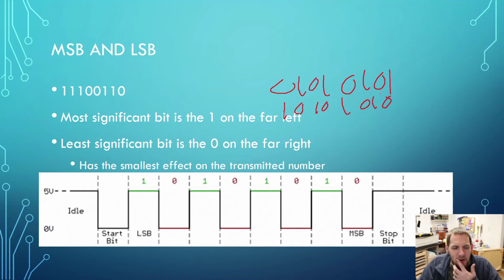So all of a sudden now your data is scrambled. You're like, why is it sending this information, what doesn't make any sense, what's going on here? It's supposed to be setting this specific code, and it's nowhere near that code. Well, that's because maybe it's your MSB or LSB. Which one are you reading first? So make sure that's one more thing that you have set up correctly. If we don't have that set up right, you're going to have some other problems.